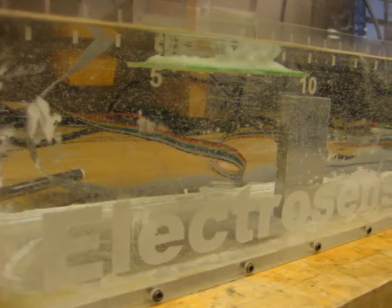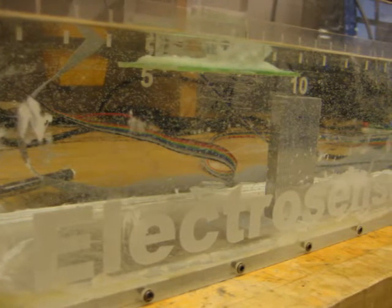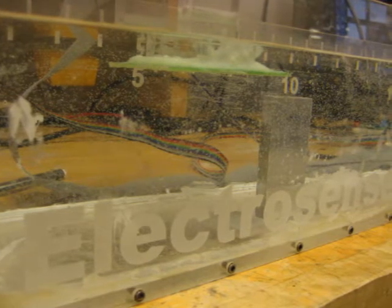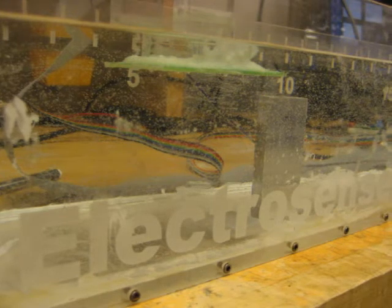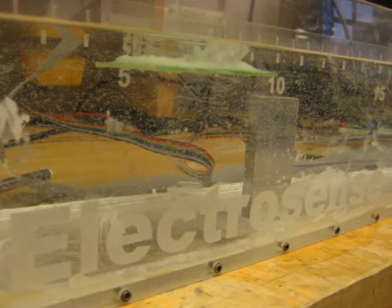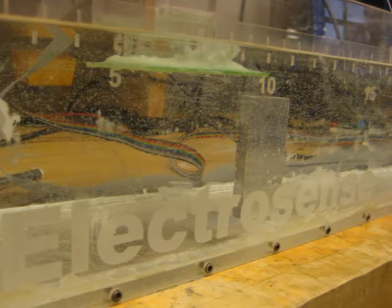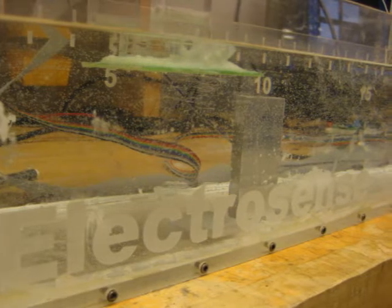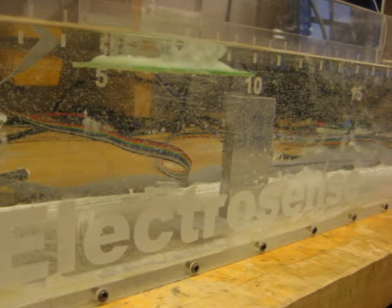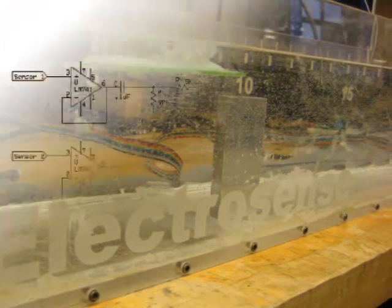Our objective is to build upon existing research currently being done at Northwestern, utilizing electrosense technology, to see if information can be derived by varying the emitted frequency. We sought to send sinusoidal waves at discrete frequencies between 100 Hz and 10 kHz, read in the sensed wave using a PIC32's analog to digital converter, and then send these waves to a PC for plotting and analysis. By mounting the sensor on a one-dimensional linear actuator, we were able to gather additional information about objects and perform object detection and identification algorithms.